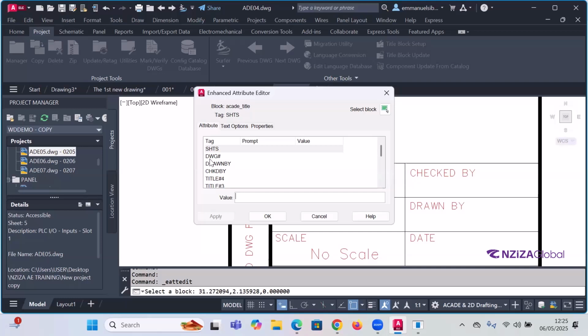They are what we call attributes and what we call values of attributes. The attributes remain there without changing, and they appear in the title block. But the value is the thing you can complete whenever you want, and it can be changed.